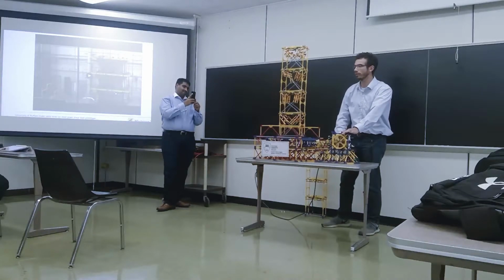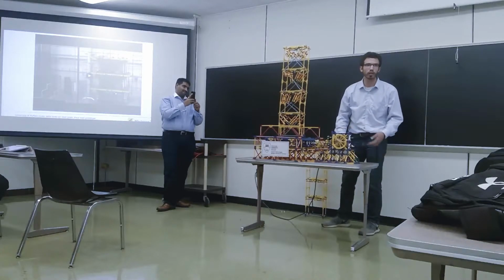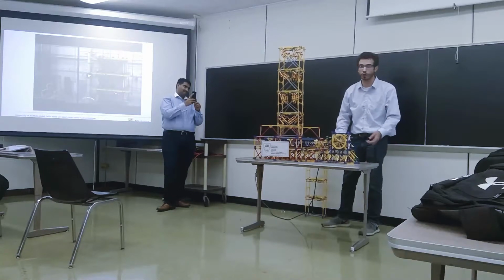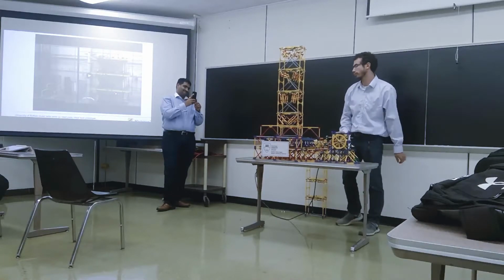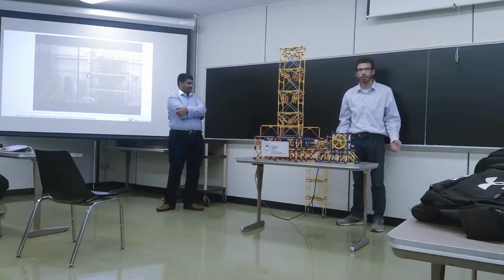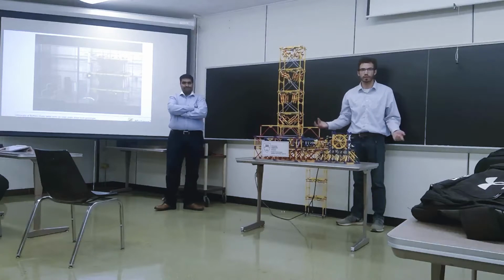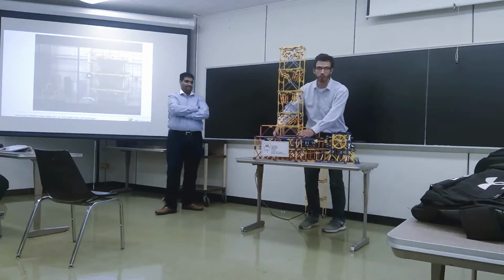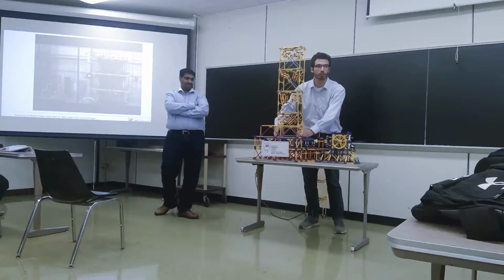So this is a demonstration that the stiffness of your building is going to be directly proportional to your frequency. And it also shows the importance of, if you're designing a building, you want to keep in mind that if it's damaged, it can lower the frequency at which it's excited. So that's something that we have to look at in my research group.